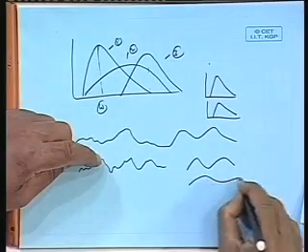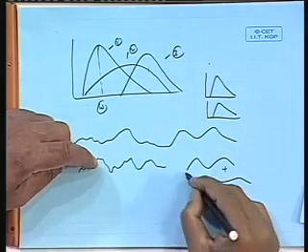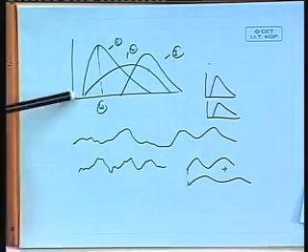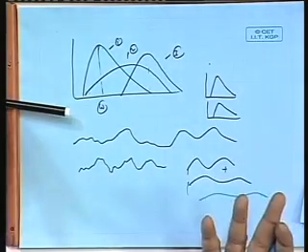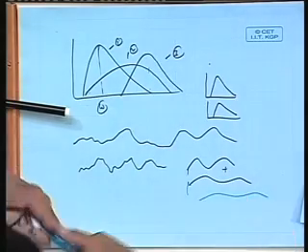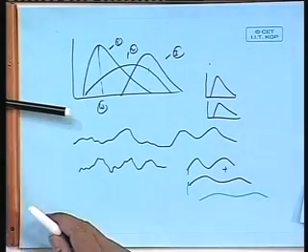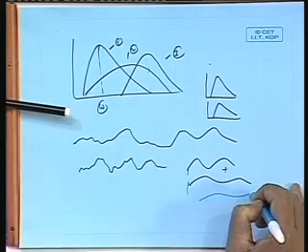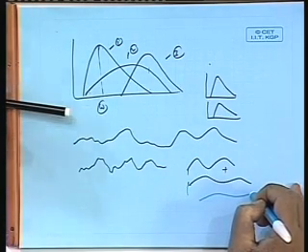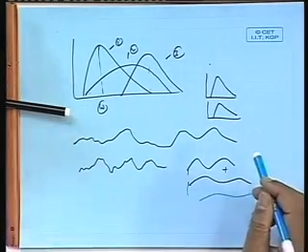The only thing is that the signal looks different simply because, if you take just sine waves and add the phase differently, they will look different. See, if you take a sine curve and another sine curve and add them together, you will get one picture. Now you simply shift this sine curve slightly. Instead of starting from here, you start from here and add this and this, and you will get a different signal. So although you get a different signal, they may still represent the same energy, because this plus this and this plus this both will have the same frequency and the same energy. Both of them will have the same spectrum, but they look different. Why do they look different? Only because their phase is different.